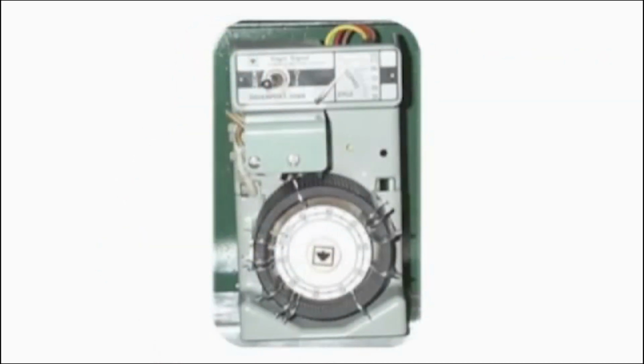The analog architecture of the traffic signals is the culprit for these phone calls. The latest and greatest controllers that we have right now are what I call electromechanical controller emulators. They are solid state, digital on the outside, but on the inside, all they're doing is emulate an electromechanical controller.